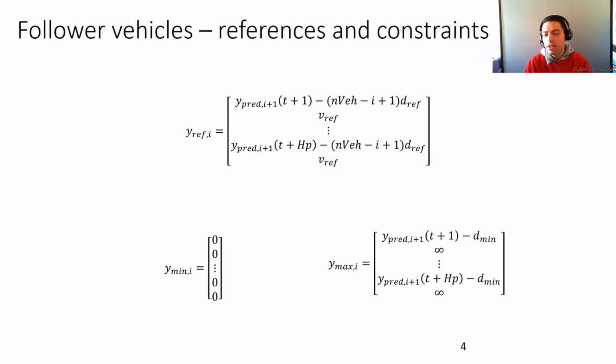Yeah, I guess I understand your question, and this is exactly the question I was also facing in the beginning, until we also discussed with another group. But the model predictive class has a step function which allows for two different kinds of inputs. So you have the possibility to include your measurements and a reference, but you also have the possibility to include your measurements, your reference, y min and y max. So using that second option, the class overrides the y min and y max that were initialized in the beginning. Okay. Thank you. Does that answer your question? Yeah, thanks.